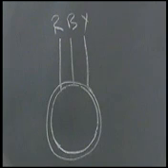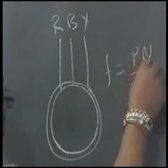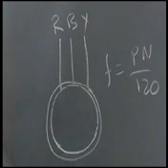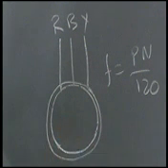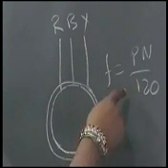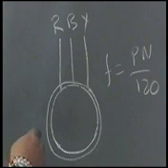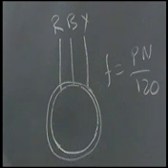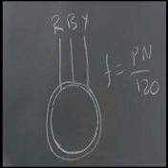And what is the frequency of that? F is equal to Pn by 120. That means P is the number of poles per phase, N is the RPM of the magnetic field produced, and F is the frequency in cycles per second.